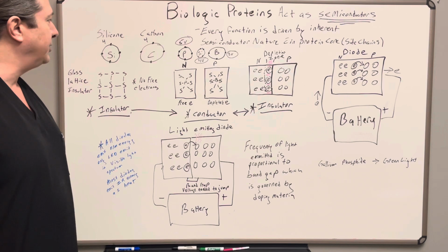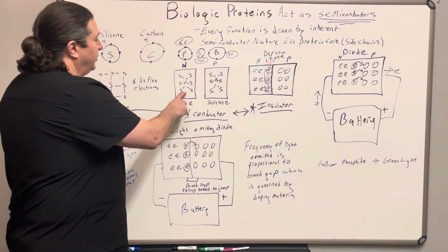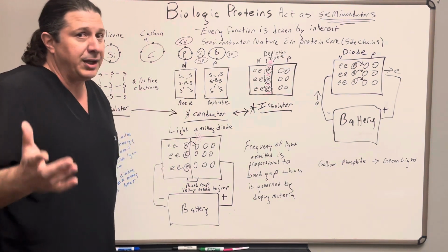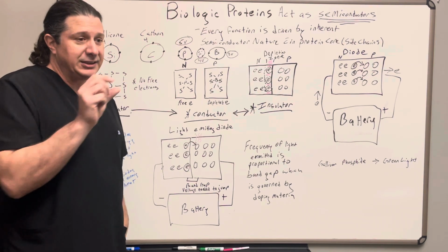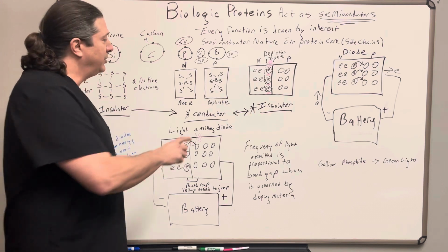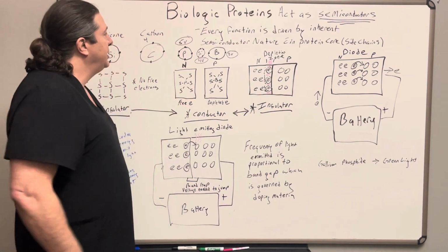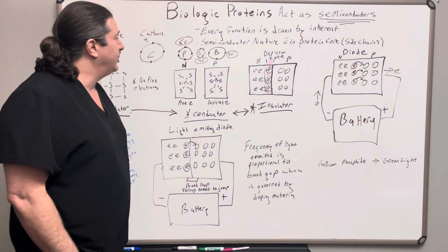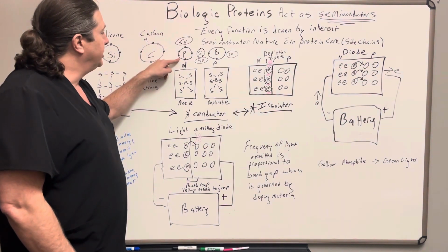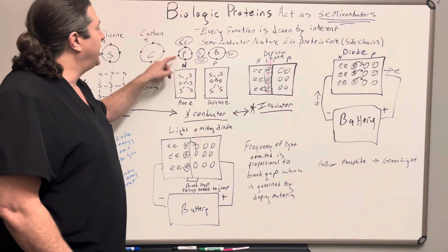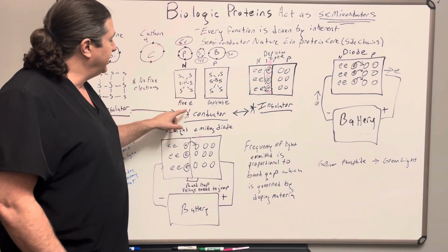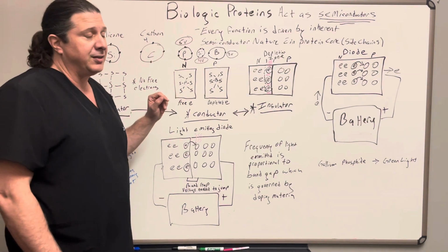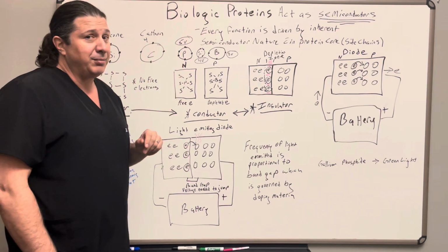A semiconductor is when you take silicon lattice and you dope it. How they dope it, I have no idea. But what they're doing is adding different elements into that glass matrix, and they're changing the structure of that matrix. So a common semiconductor we use, we'll add a phosphorus to the silicon structure. Phosphorus has 5 valence electrons. So now this structure is going to have free electrons within it. That would be called the N-type material.